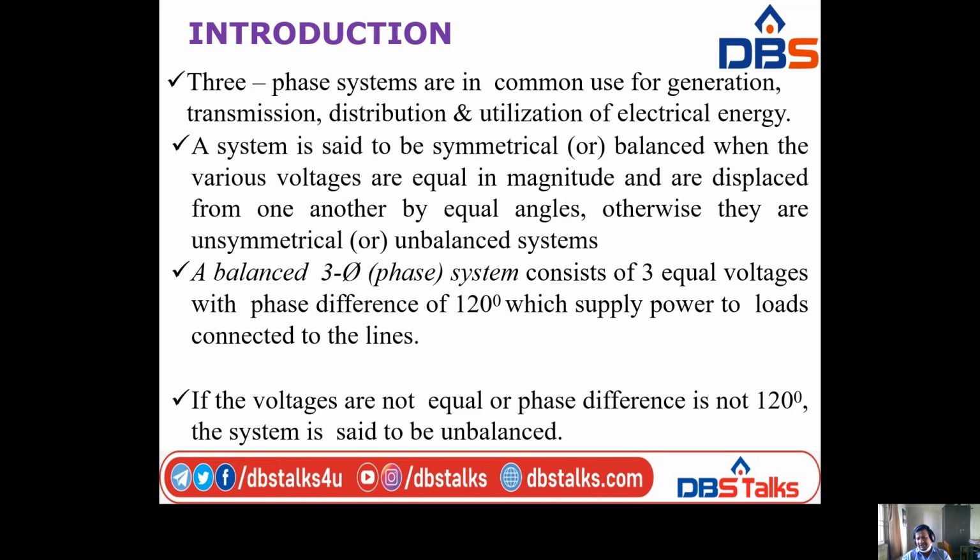Generally, a system is said to be symmetrical or balanced when the various voltages are equal in magnitude and are displaced from one another by equal angles. For three phases, the angle is 2 pi by n, that is 2 pi by 3, equal to 120 degrees.